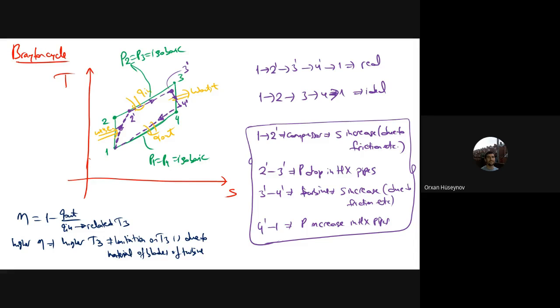But that higher efficiency is limited because if you increase the temperature, you have to select blade materials such that they can endure this higher temperature. But it is not possible, because for the blade materials that you are having here, there is a limitation. For example, it should be 1000 degrees, or it can be 900 degrees. But anyway, there is a limitation on the selection of the blade material due to the amount of the temperature here.